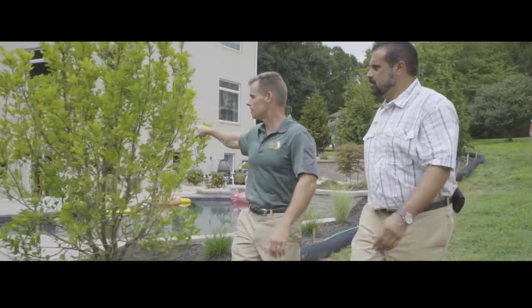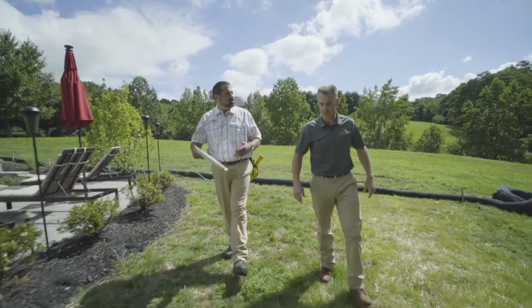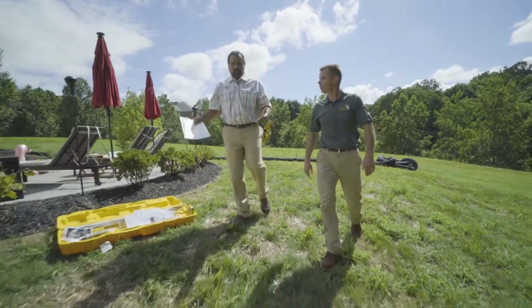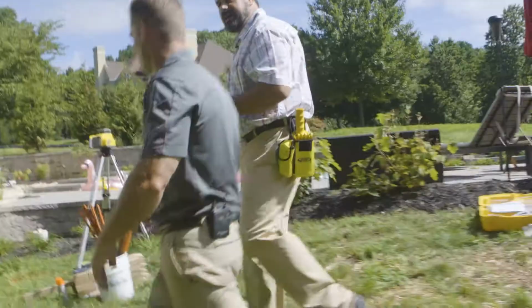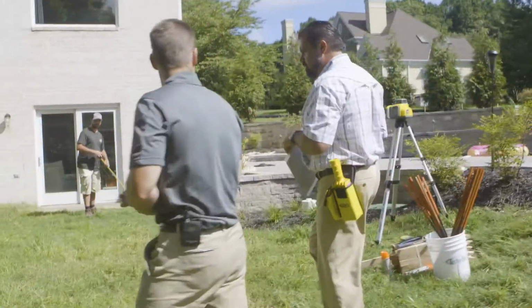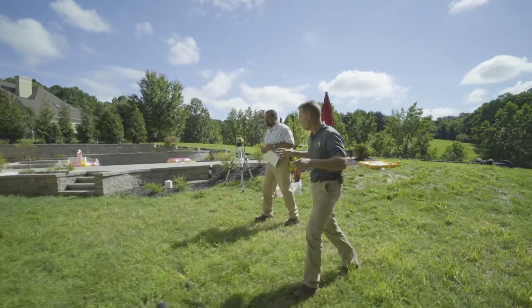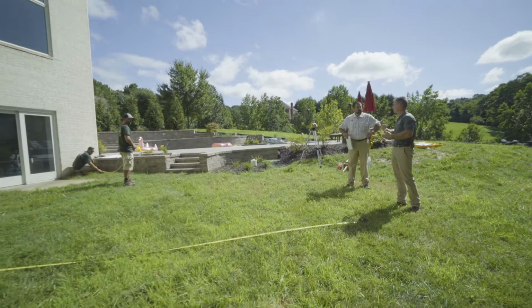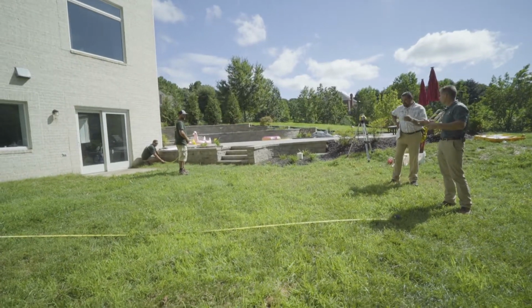So we're at the point of our project where we need to get our layout done. All the utilities have been marked. Yes. We just got to kind of paint out that perimeter. Correct. How would you kind of start a project like this? We need to find a center point that we can pull off of. Because this has a coliseum or a true circle in it, we need to find the center of that circle and then we can extrapolate everything out from there. Perfect, let's do it.